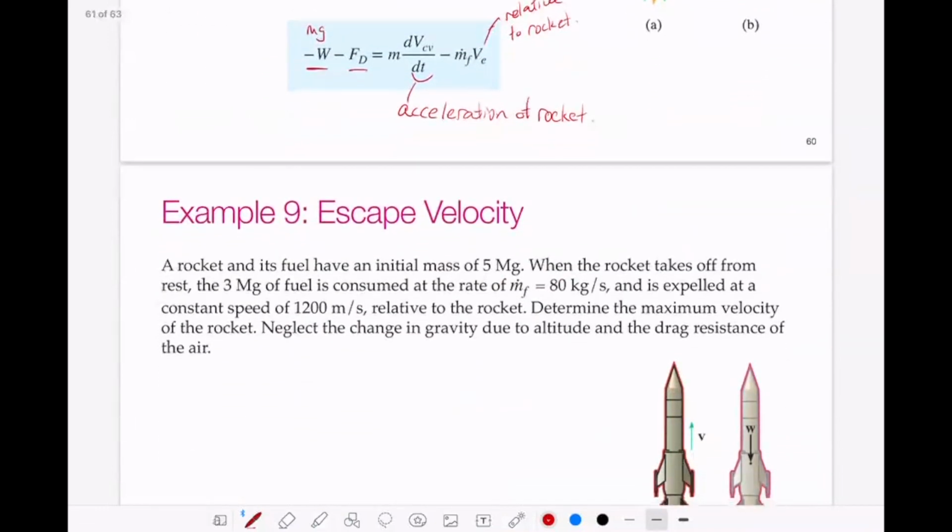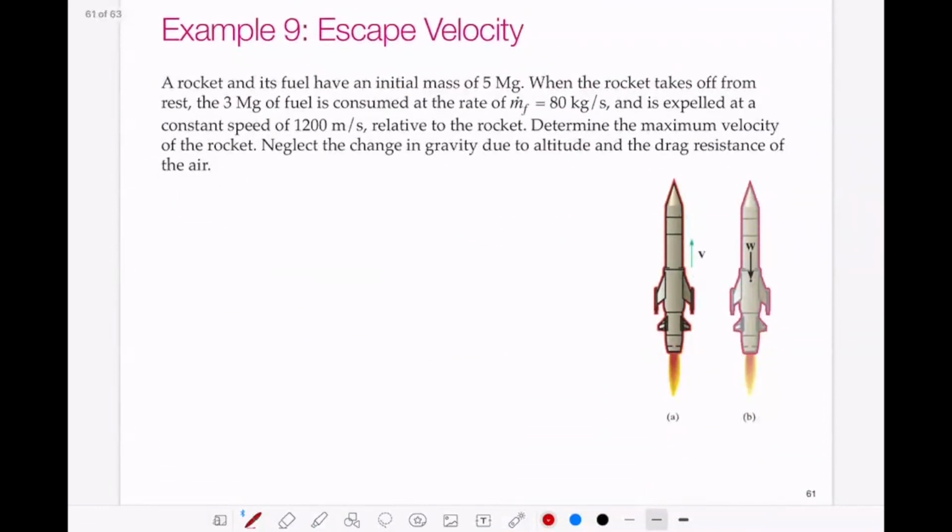All right. So we have our equation. That was a very, very quick breakdown of rockets. But if we just look at the Reynolds transport theorem, and we already did all the work deriving our equations for thrust of turbofans and turbojets, we applied the same principles and just notice that some of those terms go to 0 because there's no air mass flow rate entering our control volume anymore. So we took a quite complicated looking problem and we simplified it into this nice convenient equation.